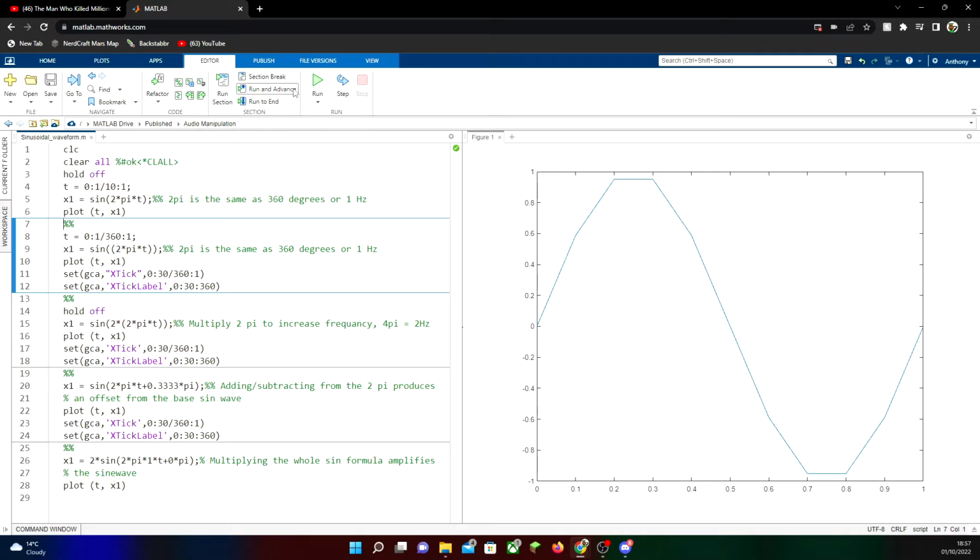Here I've made a Matlab code to discuss each part of the sine wave and their effects. Firstly, it's important to note that while the sine wave is continuous, our Matlab representation is a discrete signal, and it's important to pick the right sample rate, or samples per second, to represent it. As you can see, the 10 samples I have picked here aren't good enough to represent it, and so further on I'll pick 360 samples per second, as this number both helped with coding and also was good enough.